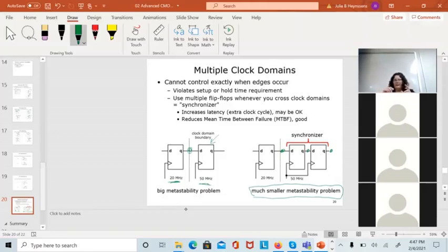And the way they get to the double data rate is they actually clock things in on both the leading and the falling edge of the clock. And it's because the clock edges aren't always stable, they jitter around and bounce with time. They don't actually do it off of the falling clock edge. They latch the first bit of data on the rising clock edge, and they put an analog circuit in there called the delay lock loop that will latch the second signal in at half the expected clock cycle.